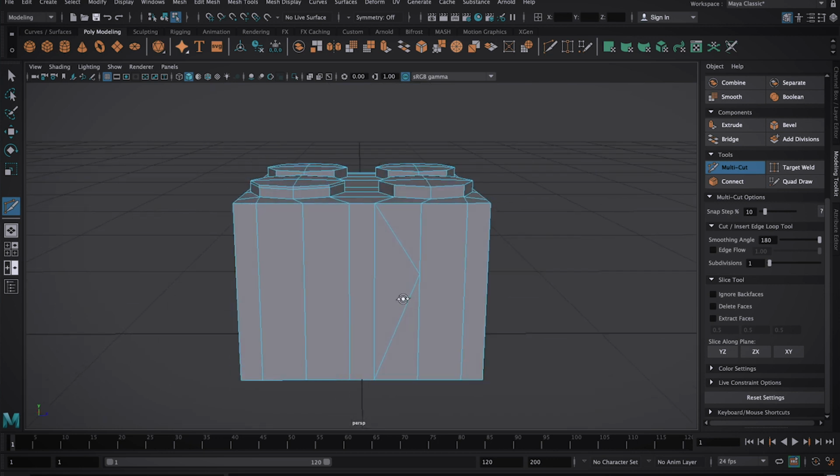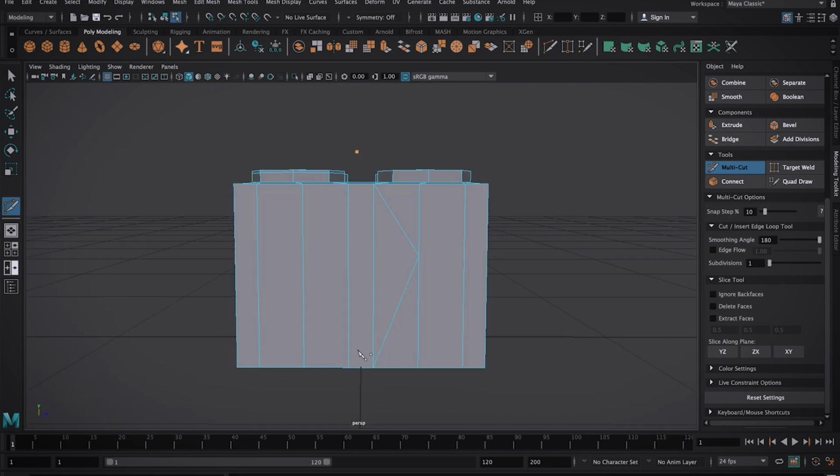The next thing is you can do a cut through. The cut through is when you just click above the object and below the object. Once you do that, you see this orange line appear. If you hold Control, you can move the points around anywhere you like to make it on an angle or whatever you want to have. If you hold the middle mouse button, you can slide the cut across your model wherever you want it to actually be, making it more precise if you didn't get it in the right spot. And then hit return again to make that cut.